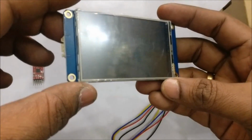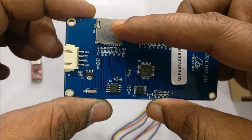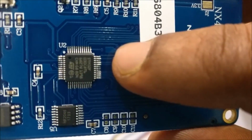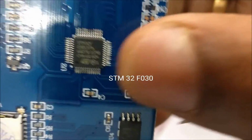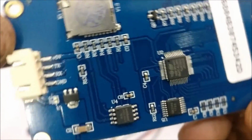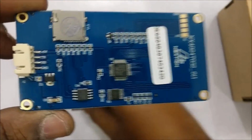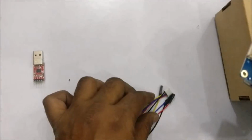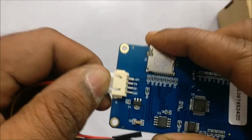This display has an interface board on the back side with the SD card slot. This SD card slot can be used to upload the TFT file. There is a 32-bit processor, STM32F030, for the interface. A connector is provided. It is serial connected to connect with Arduino. This is a simple connection: 5V, ground, TX and RX.